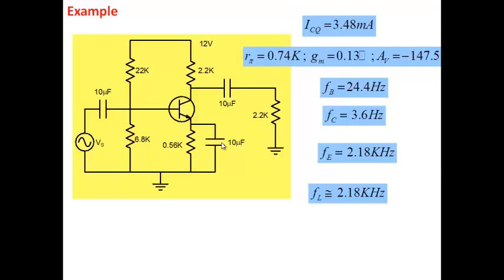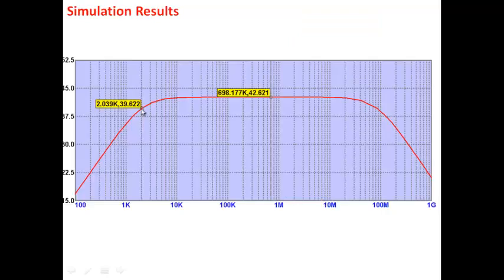Where would you use them? Where would you employ them in your amplifier? Where would you use the 100 microfarad? Emitter, right? Because what is it that we are looking for? We are looking for FL. What do I want from FL? We want FL to be as low as possible. We want to extend the range over which our amplifier will work.